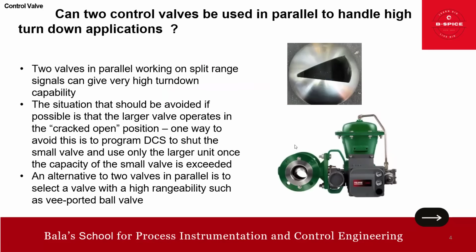Now, can two control valves be used in parallel to handle a high turn down application? Two valves in parallel working on a split range signal can give very high turn down capability. There is no doubt. No worries. The situation that should be avoided, if possible, is that the larger valve operates in a cracked open